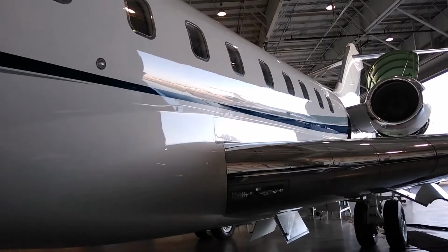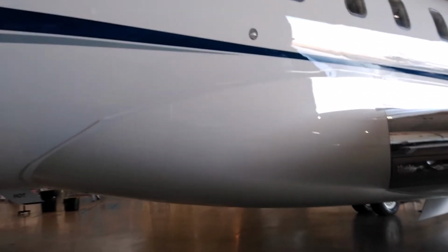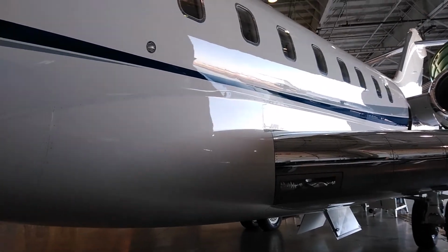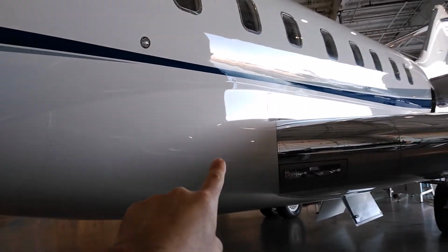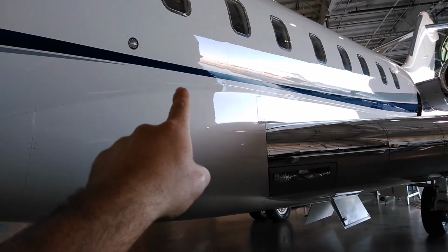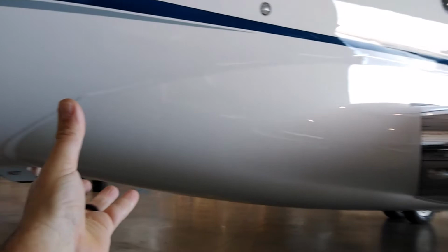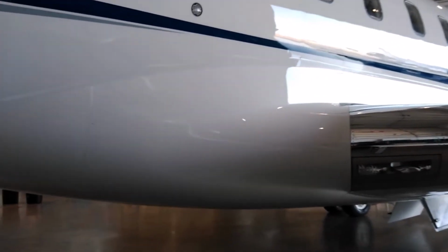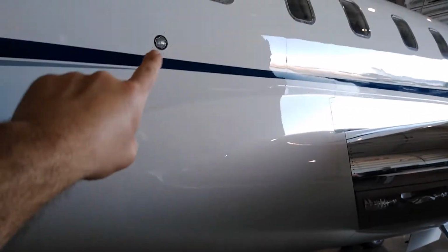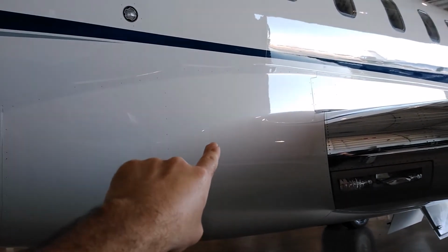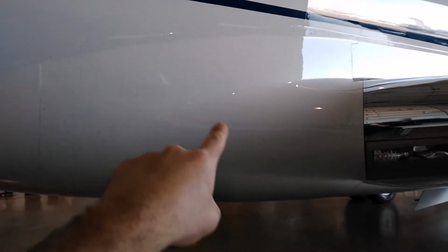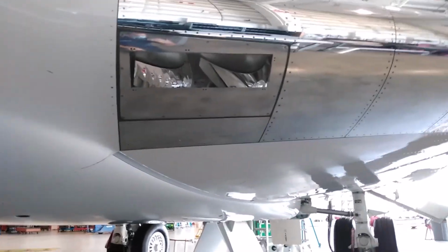Alright, now we're looking at another airplane with all the fairings installed, so you can see the comparison, the before and after. This is where we were looking at before, the joint between the left side of the fuselage, the left wing, left engine. Here's that fairing smoothing out the body of the aircraft. And that is the area where the forward pressure outflow valve is, carrying all that air under the wing out into the aft equipment bay.